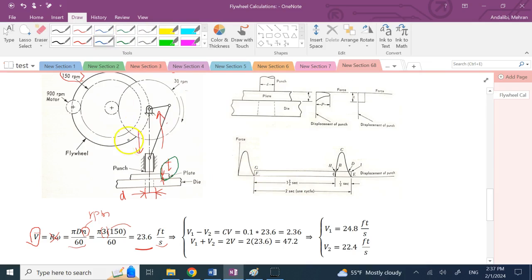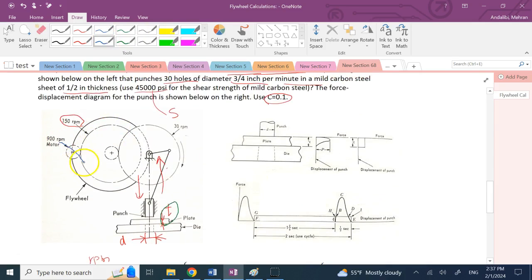It's not like during the punching we turn off the motor and just let the flywheel drive the punching system. When this punch is going through the metal, not only is the flywheel releasing its energy E, also this motor is injecting some energy into the system as well.